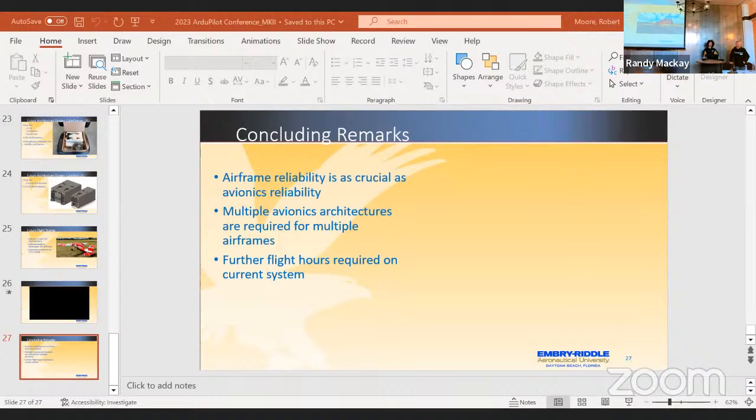Thank you. So operationally, the flights, how did you perform them? Because I noted that the times weren't really different. Did you perform the same mission over and over with automatic takeoff and landings, or were you doing something like that? All right. So with the Shock Cub, I prefer manual takeoff and landing, but I was doing autonomous loiter. That was due to a constraint of being on the RC field. It's under a letter of authorization in controlled airspace, so I kept it within a fairly confined area just to loiter to play it safe.